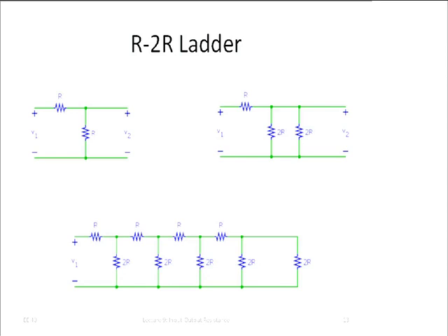Let's say in your phone, when you're talking to your phone, your voice isn't a digital signal, but your phone ultimately transmits a digital signal. So there needs to be a circuit in between that does the conversion. That's an A to D converter, and it uses, among many other features, a circuit that can establish these voltage divisions. So what we want is a circuit that takes an input voltage and then produces that voltage over 2, over 4, over 8, and so on. All right, so let's take it for now that we want to build that circuit.